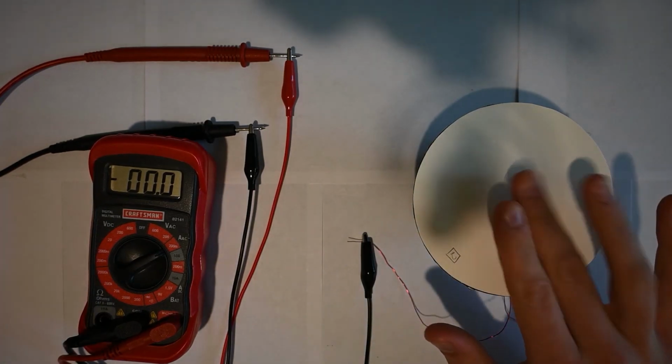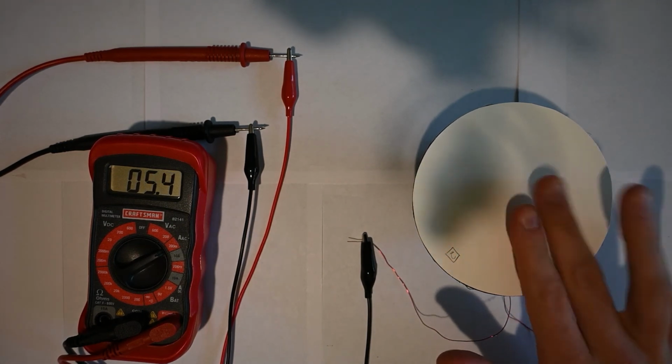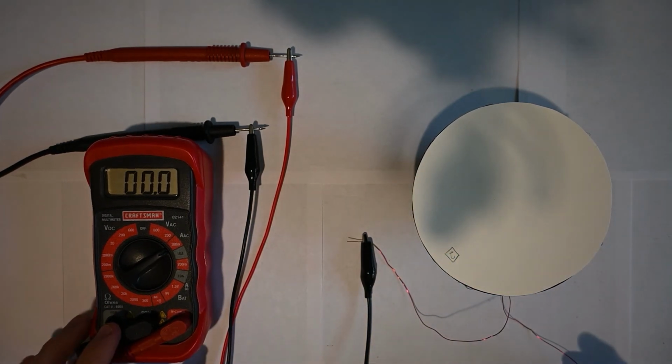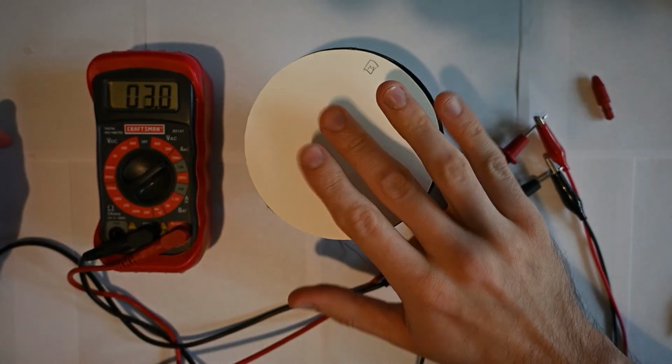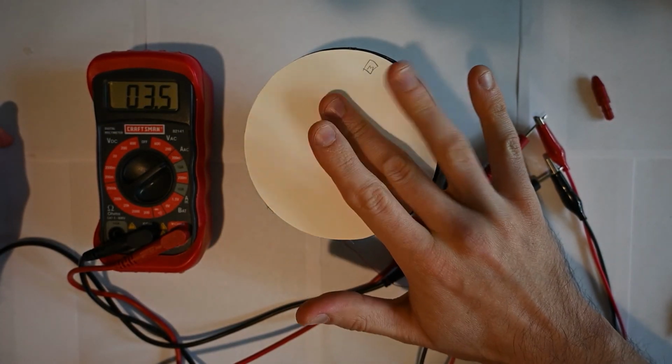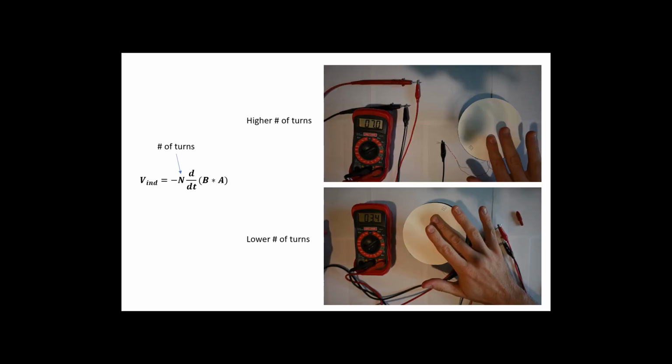Now we are going to take measurements on the alternating current generated by exciting the diaphragm of each microphone. The peak values for each microphone are listed. As expected, the microphone with a larger number of turns in the coil produced a greater current. This is because the induced voltage is proportional to the number of turns in the coil.